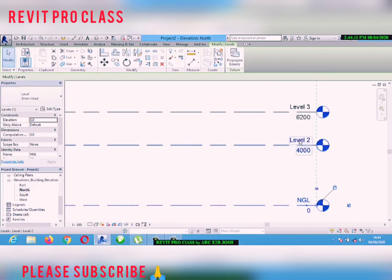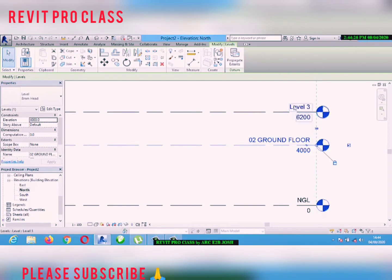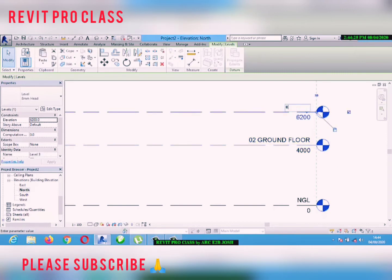The same thing happens to level 2. You double click, then you name it 02 ground floor. Click enter, click yes. Go to level 3, you name it 03 parapet base.